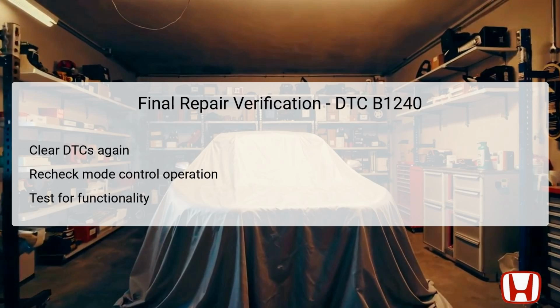After completing all necessary repairs, it is critical to verify everything is functioning correctly. Start by clearing the DTCs again using the Honda Diagnostic System, HDS. Following this, conduct a thorough check of the mode control operation, ensuring that the air distribution functions properly and that temperatures are consistent as indicated by the driver's settings.